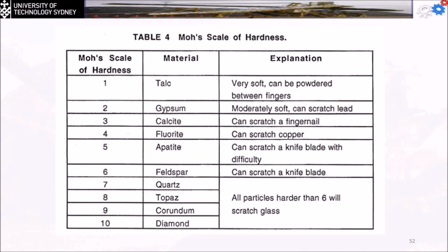After you test materials for hardness, you need to classify them? Yeah, it's going to be useful for the abrasivity of the material. The harder material is going to be more abrasive, and we can see more applications of that. So this is the Brinell scale, and this is the original Mohs scale. You can see that we are going to talk about 1 to 10 instead of the 1 to 2000 we have in the Brinell test.